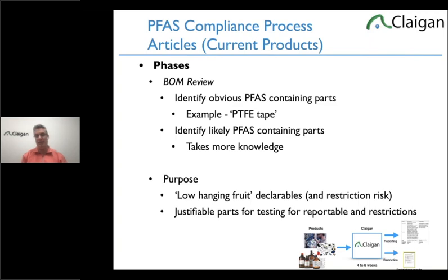And then we also go for the likely PFAS-containing parts: non-PVC wire and cable, and a variety of other material types, fabrics, etc. We say, hey, these are high risk. We want those to test. But there's a simple screening. We have a WD-XRF. It screens fluorine directly. It's fantastic. No fluorine, no PFAS. You don't have the F, you don't have PFAS. It's so easy. But you're not doing the whole product and making life difficult. I'm doing this part, this part, this part.